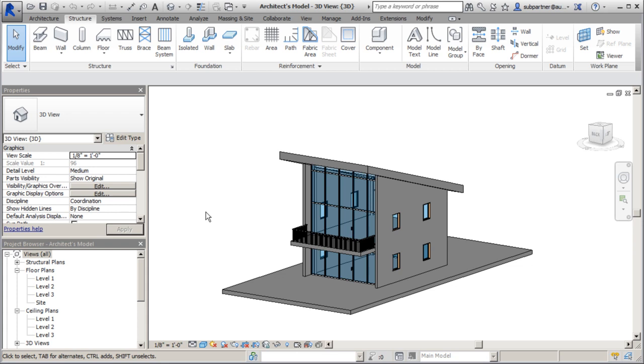We have all these different cases available to us within Revit. Now, the good thing about doing a structural analysis is that it allows design decisions to be made a little bit earlier in the design process, which means potential savings in time as well as money. Now, the goal of the overall structural analysis is to make sure that my structure meets its structural requirements. Well, what are those requirements? Stability is one, strength is the other, stiffness, economics, and also the aesthetics.